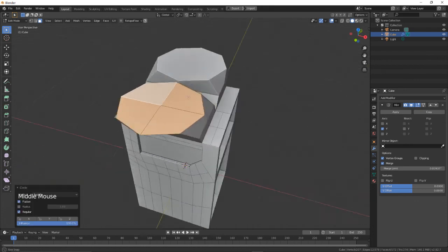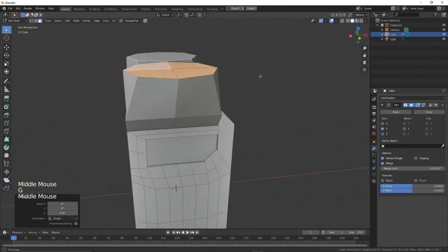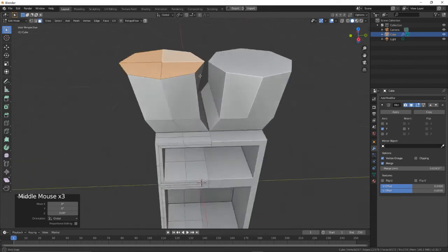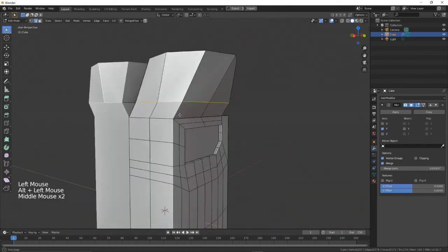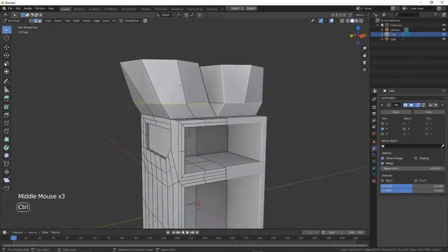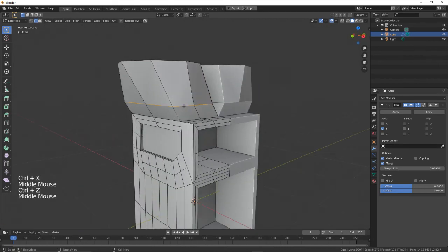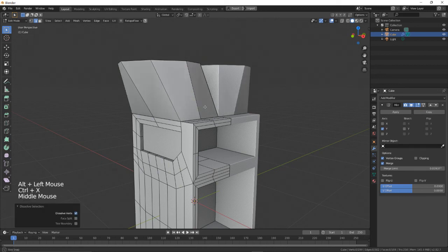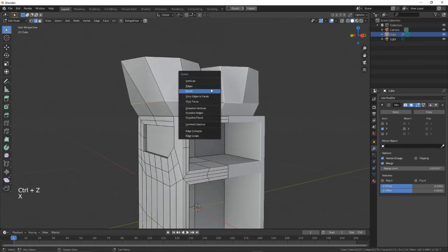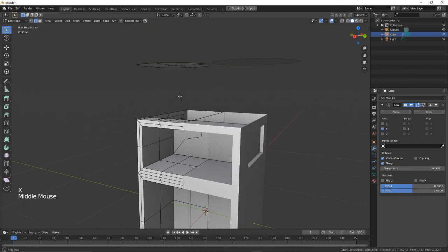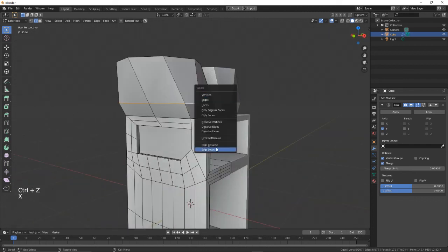I want to circularize. So now any mesh that you have selected will form a circle. This area looks a little bit wrong, with it completely flat and then suddenly changing to a circle. So if I select this edge loop by holding down Alt and selecting an edge, I can press Ctrl X to dissolve. If I was to press X regularly, it would just simply delete that geometry, as you saw there. And of course, it gives you an option to choose different deletion modes.